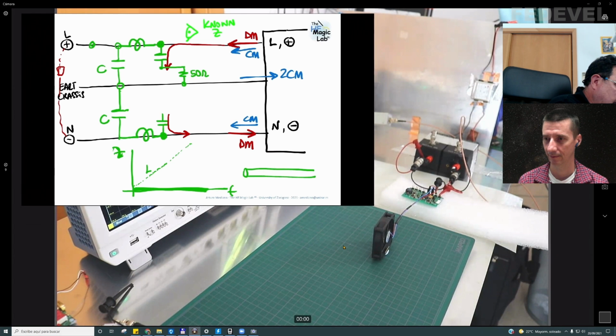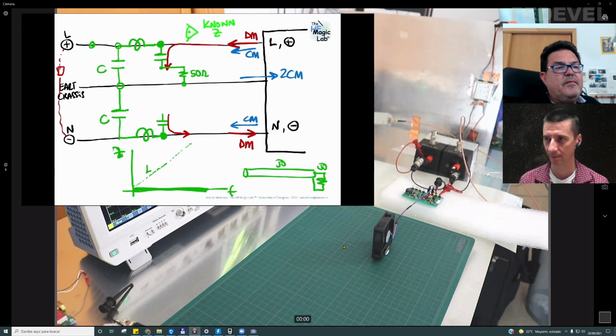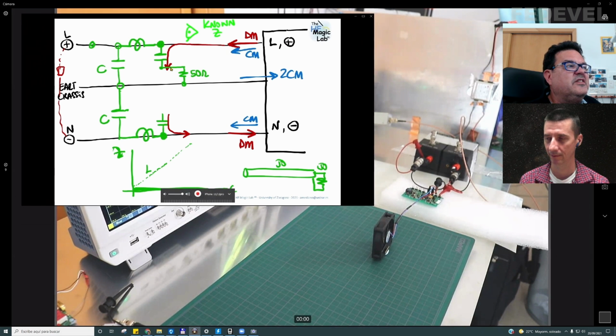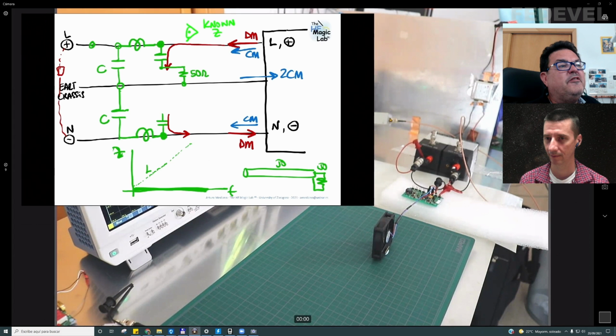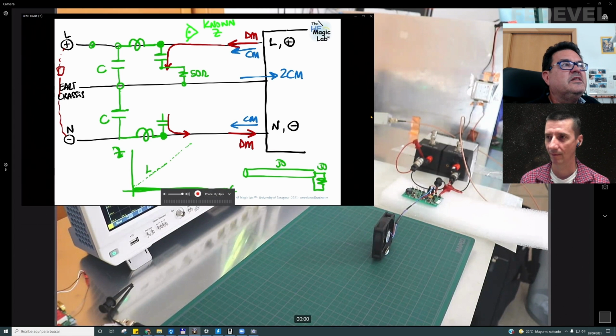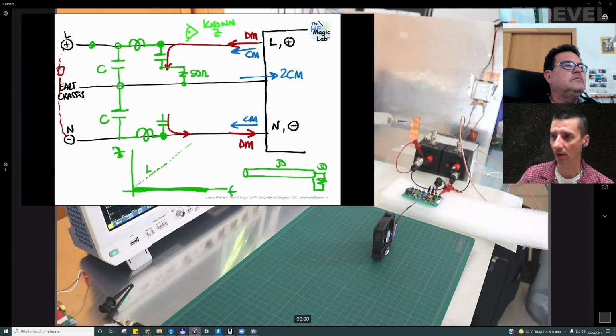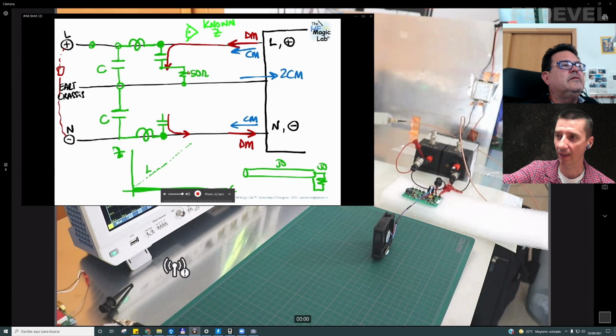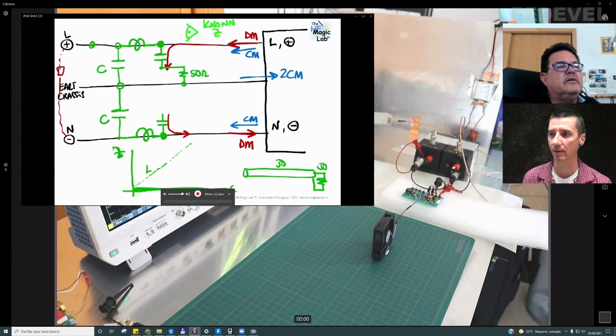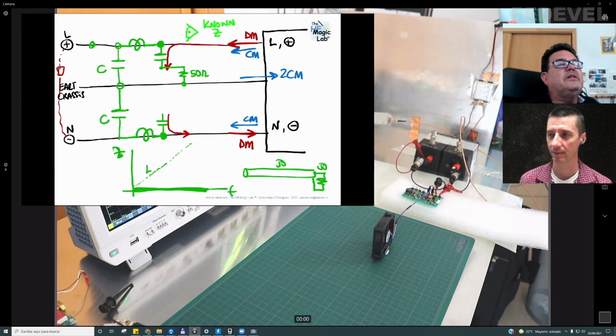Is the long coax cable terminated in the 50 ohms of your instrument. Remember, this is the connector. So if this connector is this point, the 50 ohms resistor is the 50 ohms transmission line terminated in the 50 ohms of your instrument. Okay, so that's basically the connector, or exactly. In the black box, there will be basically the connector. Exactly. You will find the connector that is the output of the line impedance stabilization network.